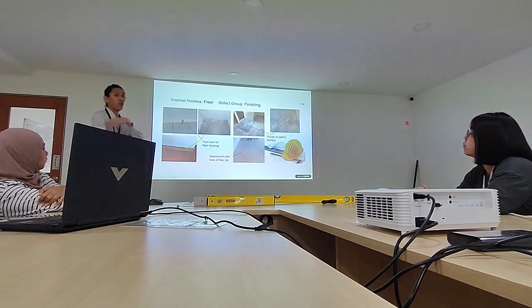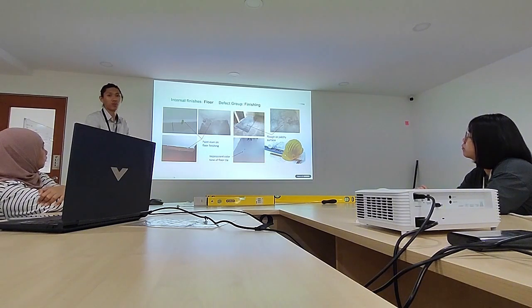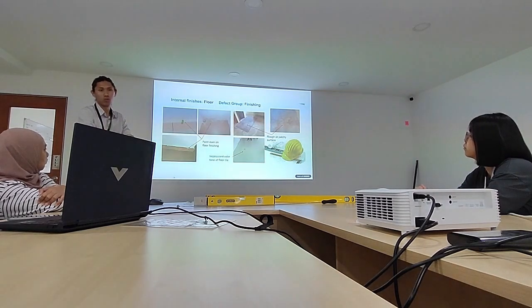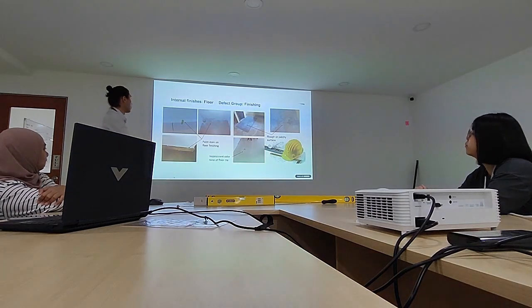For QS, it is very important that when we award the contract, or during the tendering stage, we should highlight to the vendor that this project is going to have the QRC special. The price is different because they have to put more manpower for the protection. After the check, however they do the protection, there is still more to clean, so people are needed to clean before the assessment. So this is the first thing.